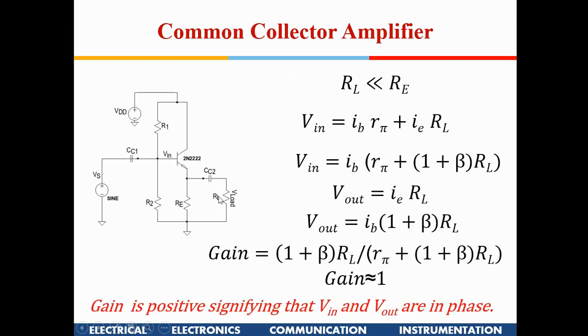Okay, now let's try and first find out the expression for the gain. So this is a CE amplifier. So let's just do the small signal voltage path. Now here I am assuming RL is much lesser than RE. So for AC signal this capacitor is shorted, so RL is parallel to RE. So instead of these three components, I am only assuming there is RL. This is the worst case scenario. If RL is greater, it is better. So we are going to tackle the worst case scenario, then automatically the rest of the parameters will fall in place. So these three components is only RL.